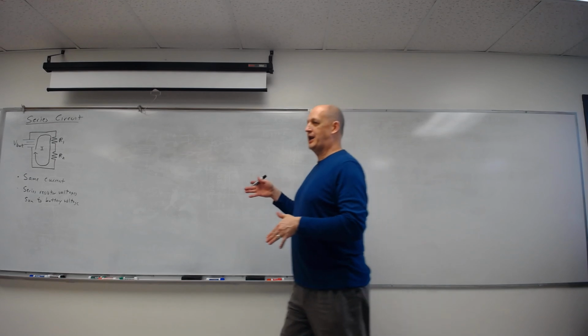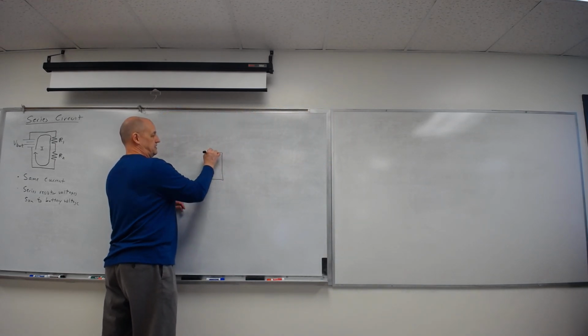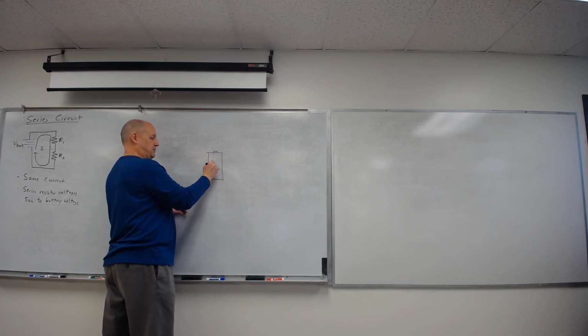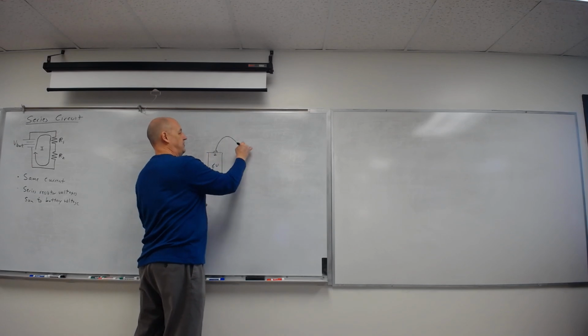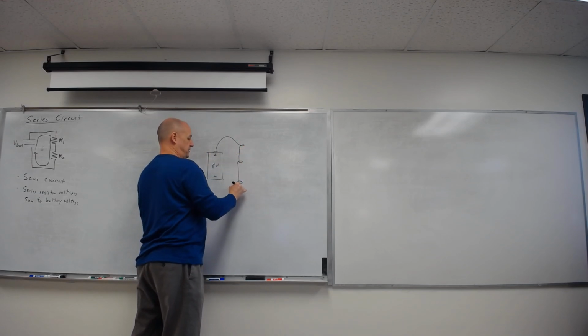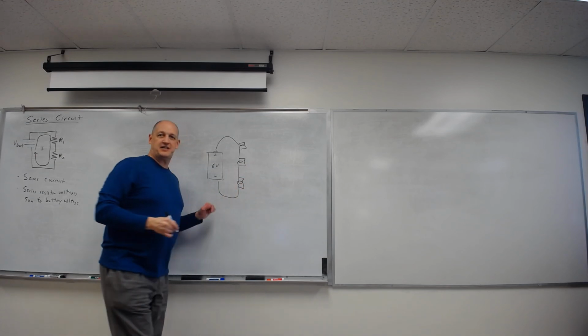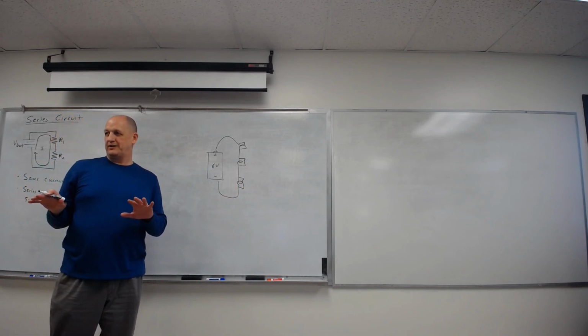You built this thing. So I'm going to pretend this is your 3 batteries in a row, 6 volts. You went out through a light bulb, through a light bulb, through a light bulb. When you measured it, you should have gotten exactly the same current through each one. If I remember right, it's about 80 milliamps, but I don't remember if that's true or not.